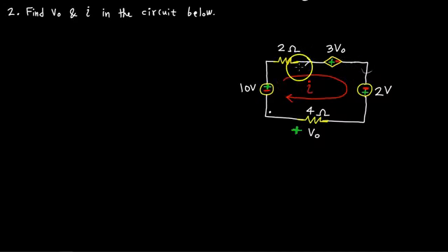I'm going to start here and go up clockwise, and see what I'm going to see for the first problem. For the first equation I have a negative 10 volts. I'm going to start dropping out that voltage. So negative 10, the unit, I'm going to drop that out. Negative 10, I'm going to go up, and it looks like I haven't labeled this, but because I have said that the current is going in this direction, clockwise, therefore the polarity must be in this direction.